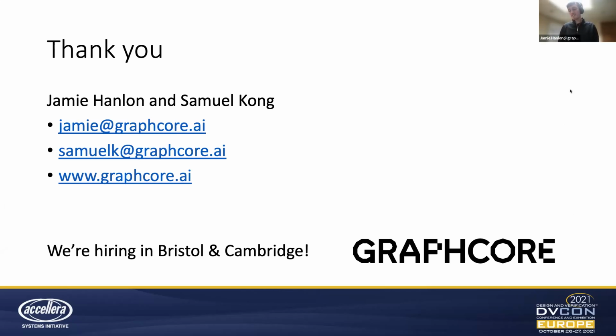The good thing about focusing this on synthesizable SystemVerilog is that it's a very small language subset. I pointed out a few open source projects such as Verible and Slang that provide Verilog front ends, but it's surprising that I've tried them and they're not all compatible with our code base. Yosys, for example, only supports Verilog 2005. So yes, it is a problem, and yeah, it's surprising that there's still quite a disparity between the tools.